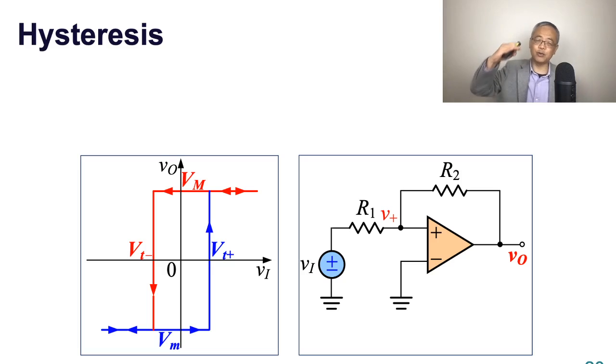When you stand on the rest state, what do you focus on? The red threshold voltage. And the reason you go to the rest state is because you crossed the blue threshold voltage. So this creates the hysteresis, which we talked about in the previous lecture.